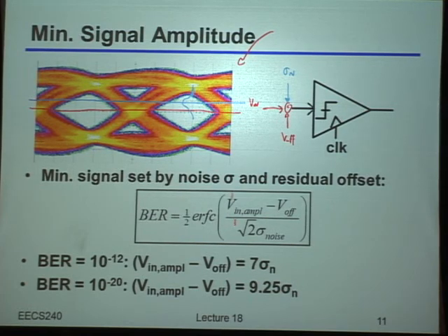I'll say some more about this later on, but it turns out that most of the fuzziness in this particular picture is deterministic, in the sense that it's very easily predictable, and the probability of it happening is high enough that for all intents and purposes, you can just treat it as, okay, it's extremely likely that I'm going to get this minimum input signal, so I should use that when I calculate my bit error rate, just because I want to make sure I actually do hit it, given that I'm going to be getting that very, very often. Does that answer the question?